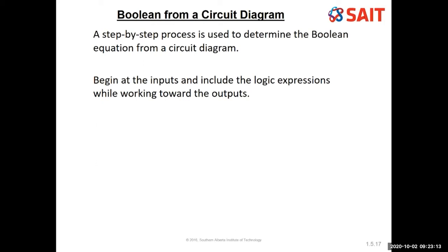So, a real world example: I have a client who wants to automate something with a PLC. Here's the existing piece of equipment. That's all we have. We've got no paperwork. We don't know what it does. We don't know what the intent was. If I analyze the circuit, the performance of the circuit, I can create a Boolean equation. From that Boolean equation, I can create my code for my PLC, and have something moved to a PLC.